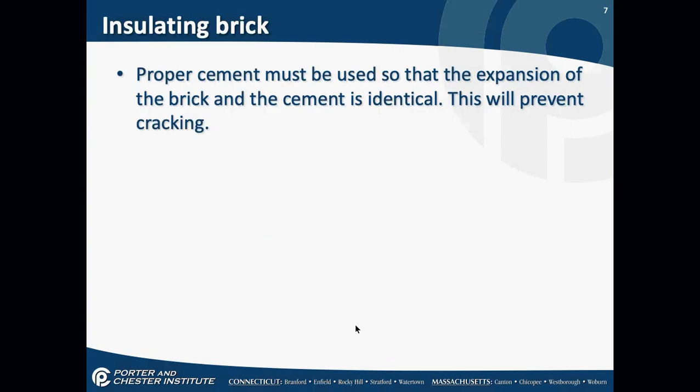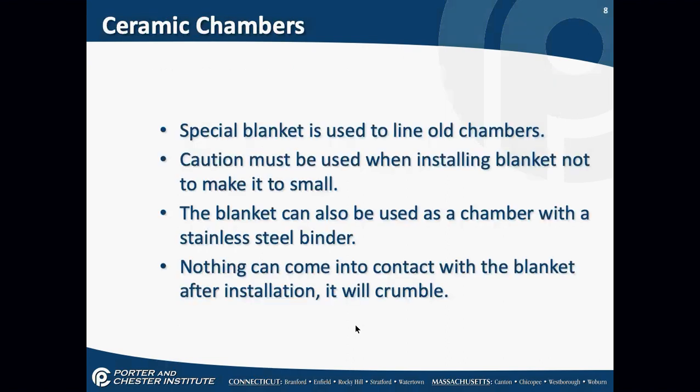Proper cement must be used when you're dealing with insulating brick. These bricks expand and contract as they're heated and cooled. So the cement that's used to put these together must have the same properties for expansion and contraction as the brick itself does. That prevents cracking, because if the cement holding the brick together expands and contracts at a different rate than the brick, the whole thing's going to fall apart because that cement's going to crack. And that would be a bad thing.